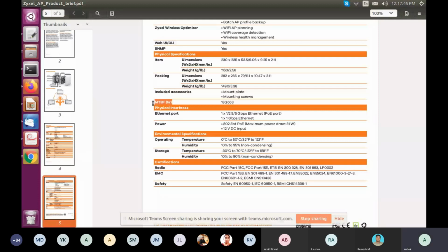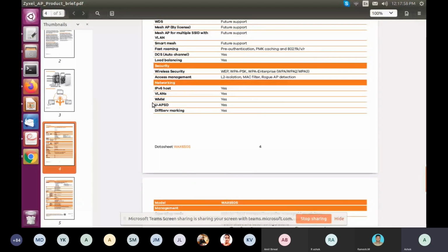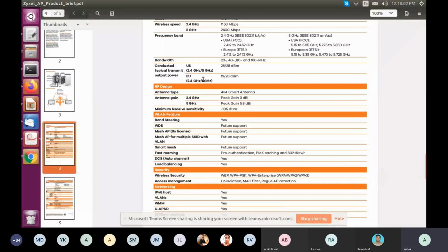And from an RF point of view, what is of interest is things like receiver sensitivity, which is minus 105, which is given here. Then the transmit power. The transmit power varies between 2.4 and 5 gigahertz in a European based system, and the bandwidths. You have different bandwidths in WLAN, at 20, 40, 80, 160, and you may want to look at all these options and include this in your model and see the performance. For example, you can typically do the same WLAN performance for this. So let us quickly do that. I'm going to do this 2828.